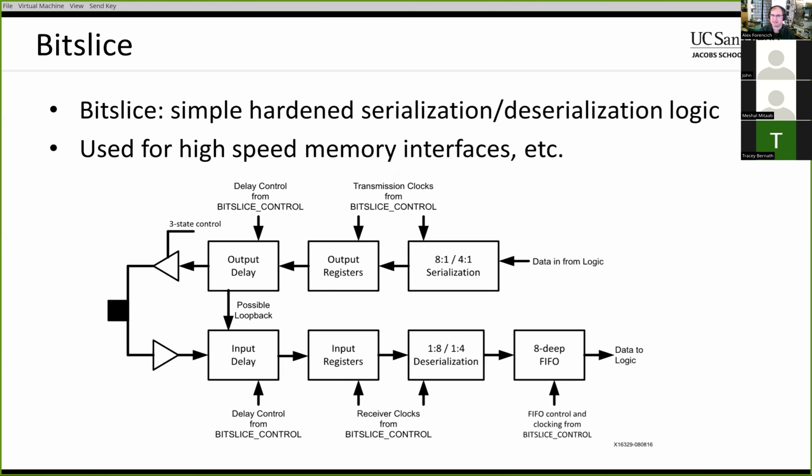So on the Xilinx devices, the LVDS I/O is handled by what's called the bit slice logic that's associated with the pins. There's actually 2 different ways you can use this I/O serialization capability, you can use either component mode or native mode. So native mode is the bit slices. Component mode is like the I/O SerDes and I/O delay blocks that you can drop down.